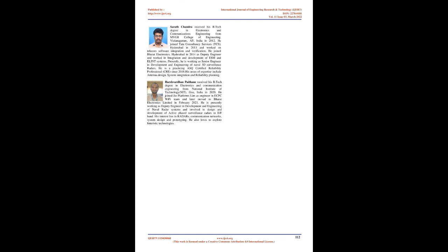7. Conclusion. A 16x16 rectangular array at L-band is considered for application and analysis of a phase-only beam broadening technique to widen the radar transmit beam in elevation. Quadratic phase weighting method is applied for N equals 16 elements in elevation, and corresponding radiation patterns for different cases of φmax, 0°, 90°, 135°, 180° and 225°, are generated using MATLAB. For validation of MATLAB generated results, two cases, φmax equals 0° and φmax equals 180°, are considered for simulation in CST software. All the antenna array inputs are kept constant for CST simulation except that a folded dipole antenna is used as antenna element in CST.